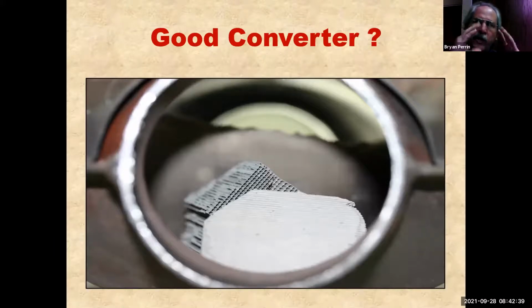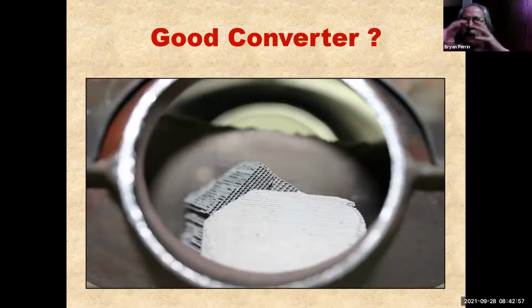But the big thing we're doing is, when I showed you the picture of the catalytic converter, we had the metal shell, we had the biscuits, and there's a blanket that goes around the biscuits. Now that blanket is kind of soft because during shipping, it can change a lot of altitude, different temperatures, things like that. So it has some cushioning effect. But I don't want that cushioning effect on the vehicle. I want to firm it correctly in place. So once we heat it, that blanket actually pops and becomes firm, where it securely mounts the biscuit between the shell and the biscuit, but still has some flexibility for the different expansion and contraction rates.